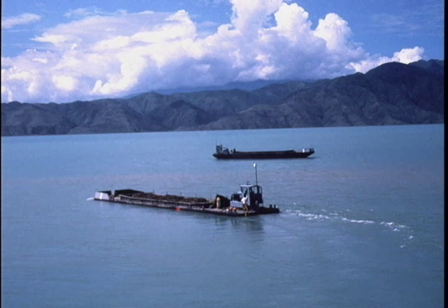Here is a picture of one of the barges being loaded, and here a picture of 2 barges as they traversed the reservoir. It is significant to note that the open part of the sinkholes penetrated no more than about 1/3 the blanket. This is the result of the loss of the fine fraction from the blanket. The remaining coarse fraction occupies the lower two-thirds of the sinkhole. Leakage through a sinkhole certainly was much more than leakage through a corresponding zone of undisturbed blanket material. Nevertheless, as Arthur Casagrande, who was on the Board of Consultants, pointed out, the sinkholes amounted only to the equivalent of pinpricks in the blanket.